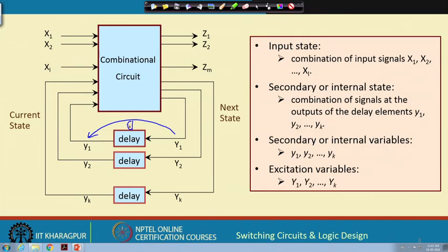I showed here a gate, let us take that same example. After this gate delay, this will happen. So, when some input is applied, the circuit will go through some transition region, some temporary states before they get stabilized into y 1 to y k. There is a concept of stable state that comes into the picture here.